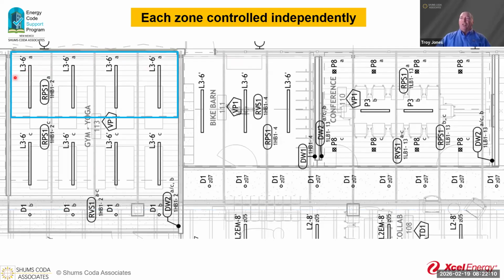What we're going to be doing is taking a look at the electricity in these zones here. Make sure that we're over the 300 watts or over the 150 watts, and that will make that determination as to what we have happening. You can see the secondary zone coming in here. So we took half this window height and came over here, added that up. So this is our primary zone. This is our secondary zone here. And then we would go to our lighting schedule to verify what's going on with the wattages.